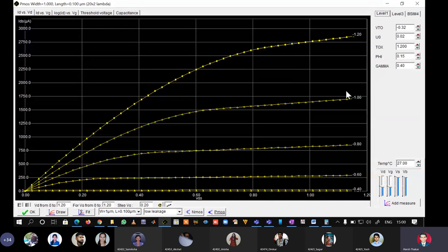I repeat, because the mobility of an electron is 2 to 3 times the mobility of a hole. That is why this difference in mobility is reflected in the maximum current produced by an NMOS device. In other words, because NMOS produces 2 times the current produced by a PMOS, we say that the NMOS device offers half the resistance of a PMOS.